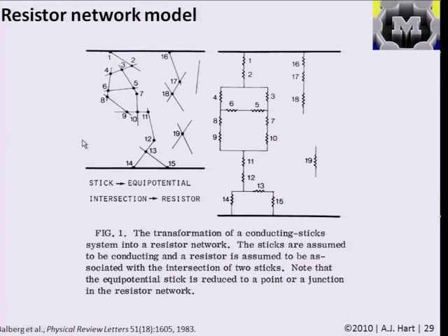And if you added up all the individual nanotube resistances and junction resistances, you could get a final resistance for this network. And by using this in combination with some statistical math, you can derive the origin of that percolation curve and predict that general power law scaling we saw on the previous slide. So this is from the old Balberg paper, which is up for your reference if you wanted to look at it.